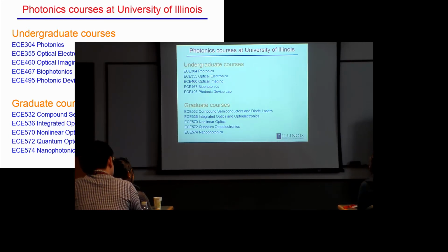And so in most high-performance interconnects, they use what's called single-mode fiber, where they very carefully craft the size of the core, the high-index region, and the cladding around it, so that one mode can transmit down that waveguide. They do that basically by controlling the geometric size, because if you make it small enough, only one mode can travel.